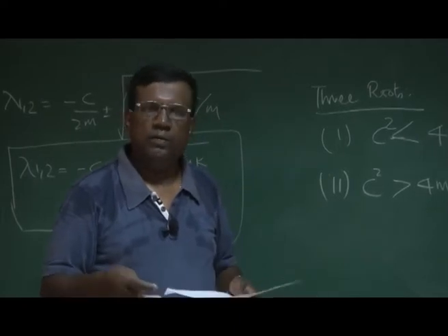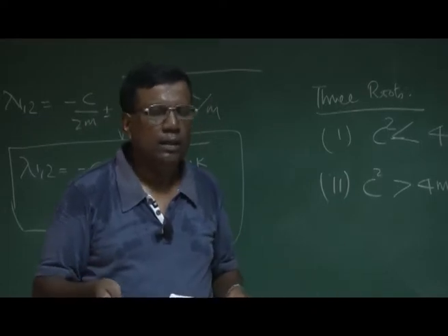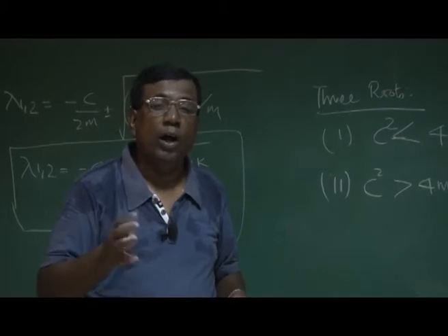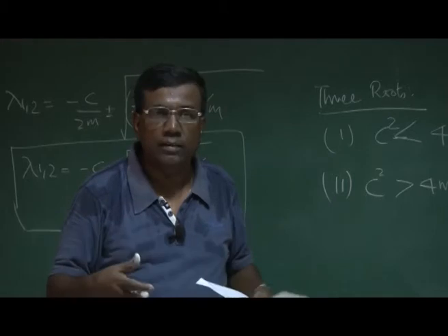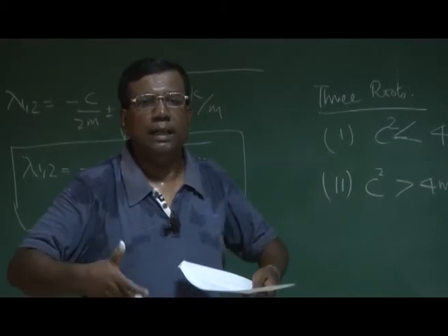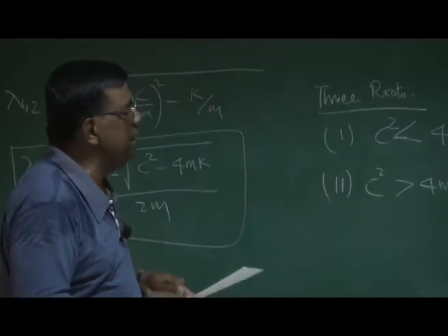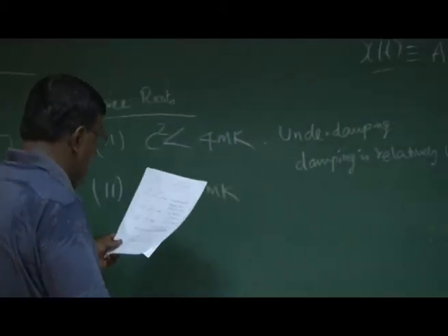So there will be friction, and some energy will be lost through air friction. It will have some damping. But if I replace the air by water or oil, the damping will become large, or c value will increase. So it will be referred to as larger damping compared to only having air. Clear? So from that engineering sense, please understand when I talk about under damping and over damping.